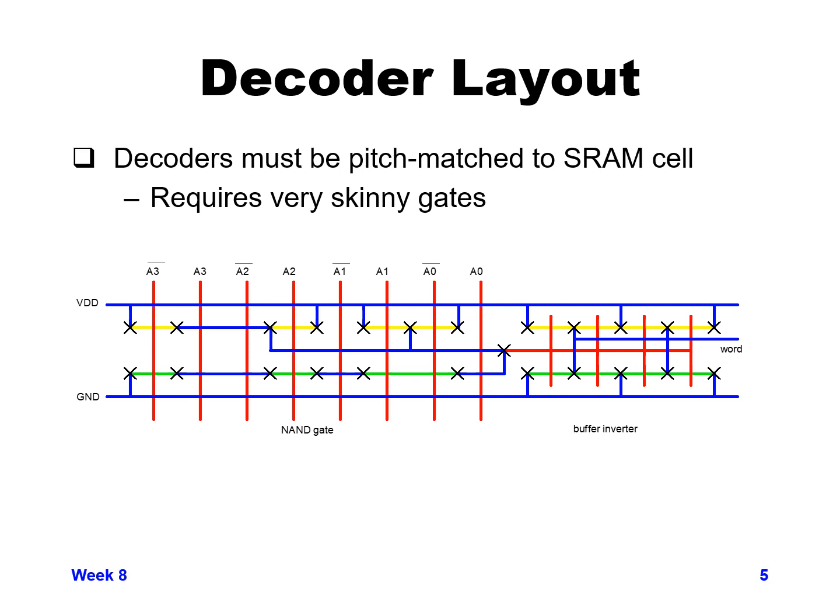So the decoder layout in general, as it's hooked up to an array, is not going to be our standard cell library. It's going to be a specialized library that's specifically for decoders going into these arrays. So that's the main reason why I'm presenting this slide.